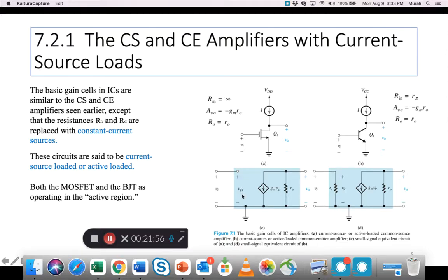But there is a voltage VGS, which is most likely this voltage. And the current, which is the model that we use, that means the voltage here is converted into a current. That current is the product of transconductance times this voltage, right? In parallel, there is the same RO.